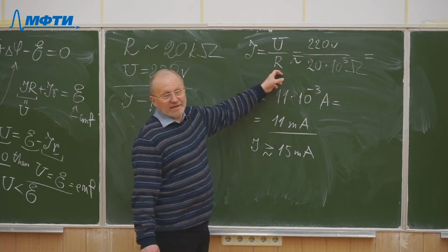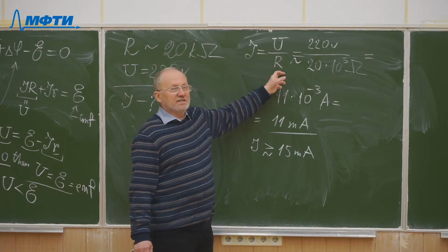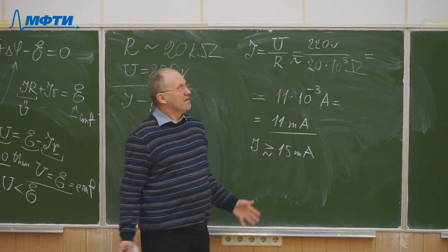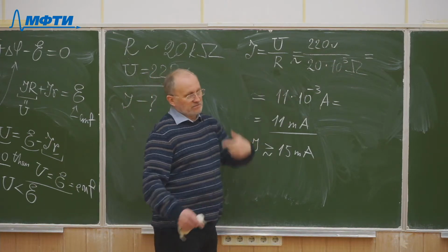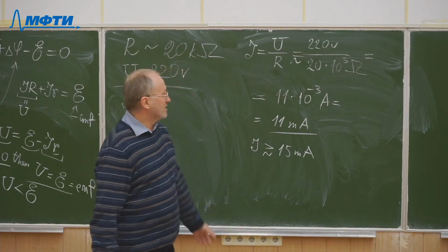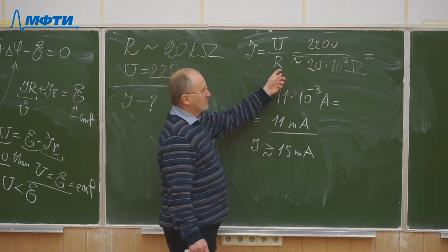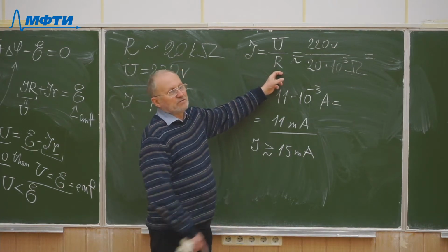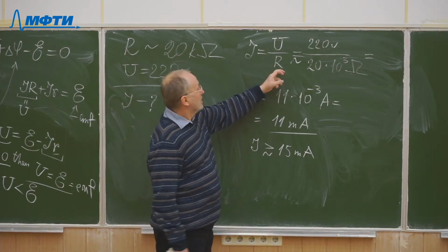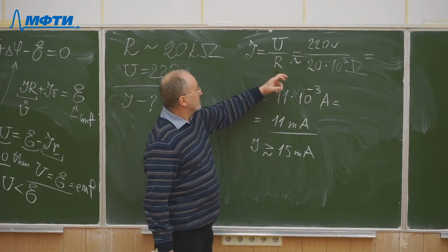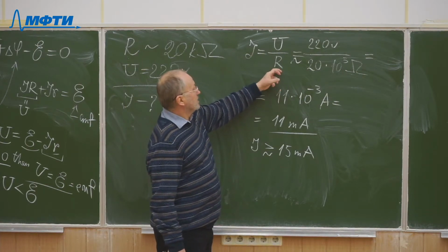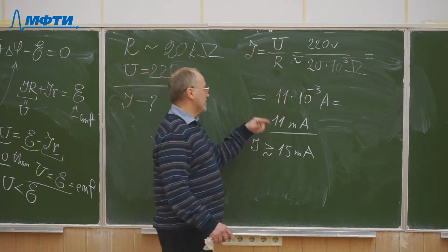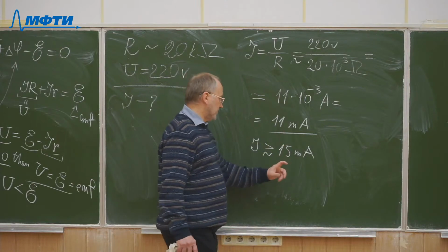If you stand on a specially designed rubber mat, then the overall resistance will be high and the current will be very small, and that will not be very dangerous. But if there is no special rubber mat under your feet, then the resistance may be very small due to the material of the floor. And then again, the current will be much higher.